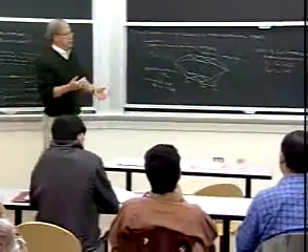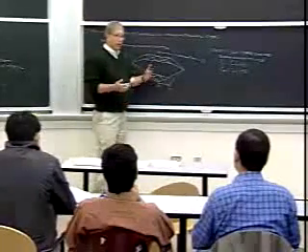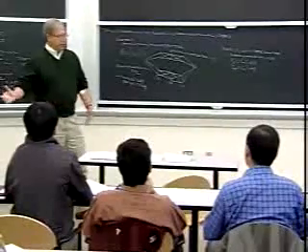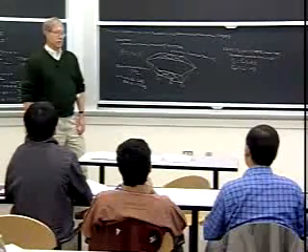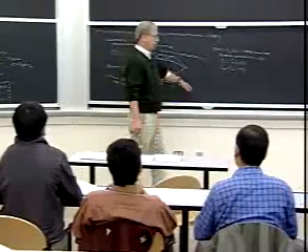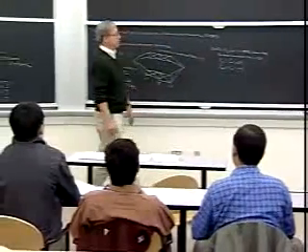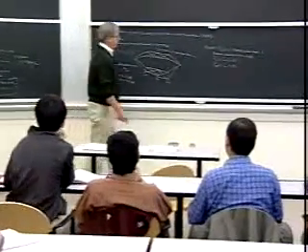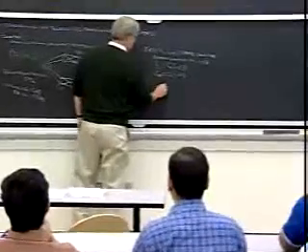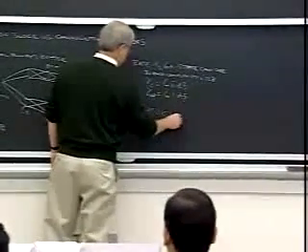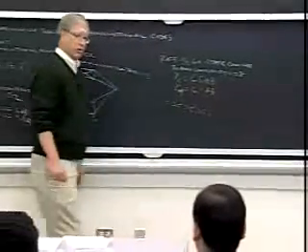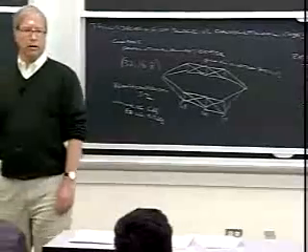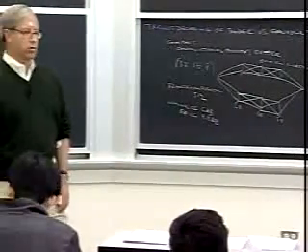First of all, they obviously naturally are well adapted to the trellis idea. They are linear time invariant machines that just have very nice regular trellises. So they're naturally adapted. But also, you know, they have exactly the right, rate 1/2 code is diverge, merge, diverge, merge, diverge, merge forever. If you want to make it into a block code, you can terminate it, or you can tail-bite it, which is something we're going to talk about shortly.